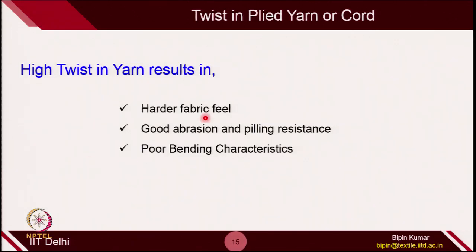So, twist is extremely important from the fabric point of view. If you use high twist, you will feel the fabric is a little bit harder, but it will result in good abrasion and peeling resistance, but unfortunately it has poor bending characteristics.